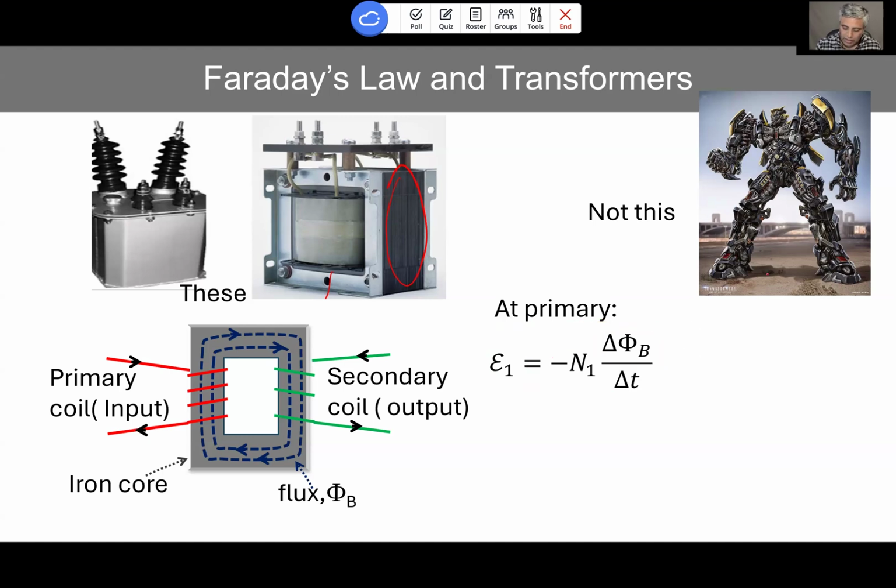Okay. So how do we change flux? As we talked about, if we look at the definition of flux, it is the product of the area of the coil, B, the magnetic field, and cosine theta. Okay. So now you can change the angle. So maybe you can do something like that, and you change flux, or you can change the area of the coil. Okay. So in a transformer, you cannot change the area of the coil anymore because once you have a transformer, it has a fixed coil. So the area of the coil is going to be fixed. And similarly, they are oriented in such a way that you cannot change the angle either. So that means the only thing you can change is the magnetic field.